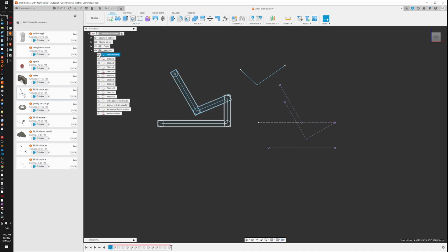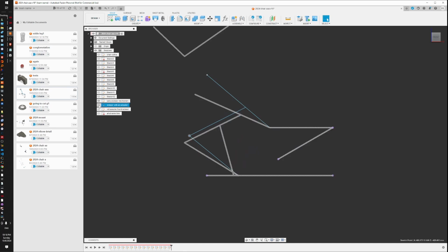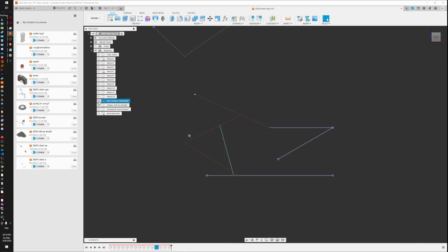Yes, kinematic. So let me show you. Let's assume that I've already found the scissor mechanism that I want. So this is the piece here. As it extends, it'll bring it up, and as it contracts, it'll bring it down. Those are the two positions that I want it to be in. If we've already found them, let's attach the actuator. Let me go in here and just choose some random numbers, mix it up a little bit.